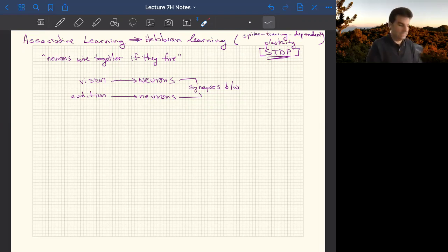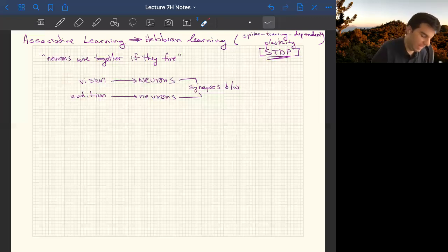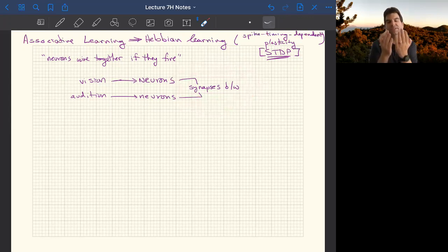So the point is that you're learning a pattern. Of course the pattern has to already be in the inputs, and there has to be topological closeness between the neurons for them to learn that they should wire together. But if you already have enough potential, and I'll show that when I show a crossbar network as an example of artificial spike timing dependent plasticity, we'll see an example in the artificial case on silicon, where you set up all the potential connections, but only the connections that correspond to the patterns are reinforced, and that's how the learning works.